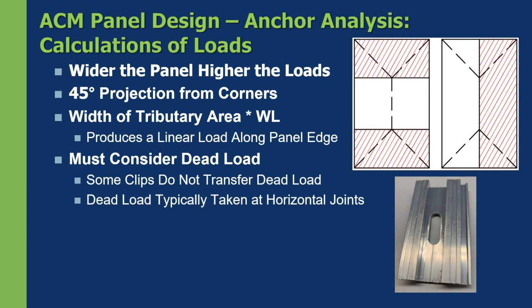are going to provide load for the panel. So on the left side, those smaller little rectangular hatched red areas, those are going to be providing loads to the shorter side of the panel, where the right side is going to be providing the load for the long legs of the panel. Now don't forget, for these situations, you're going to have panels right next to each other, so that load's going to be doubled.